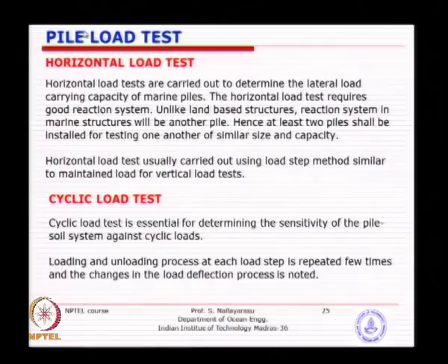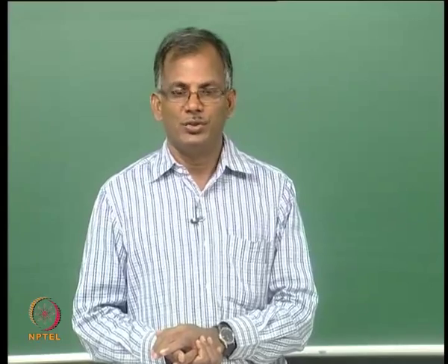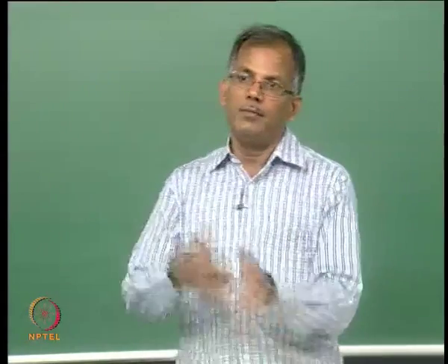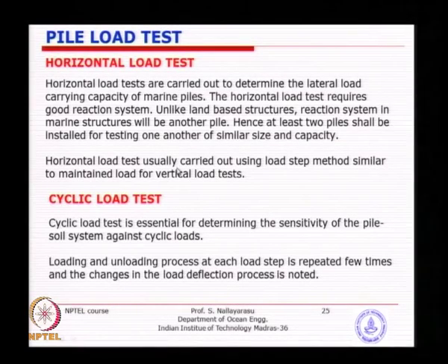But when you do a horizontal load test, you need to have firm ground or firm support condition just to measure the horizontal displacement of the pile, and also to transfer the reaction from the jacks, which is going to be a big challenge. So doing it onshore itself is a challenge, then when you are doing it in coastal or offshore conditions, it is even more challenging because you have to design a system stronger than the test pile itself and install it. And also you can carry out cyclic load test in cases of coastal structures where cyclic behavior is required for degradation effects.